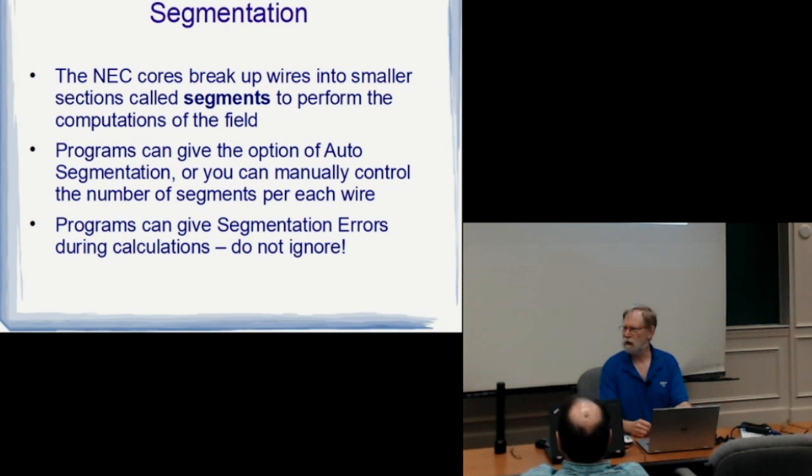And the answer is, there ain't no good answer. It's sort of like radials. It's like, keep adding more until you see things settle down and stop changing, and then stop. You don't have to add more after that. If you have too many segments, with the free version of EZNEC 6, it's going to stop working because that's the limitation of the demo version.